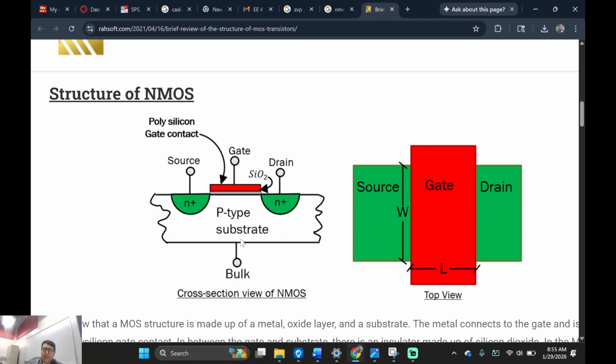So in industry, you have 2 types of substrates. You have the P-type substrate and there's an N-type substrate. But generally I've never seen an N-type substrate in my 5 or 6 years of working with IC design. Typically, it's always a P sub, okay? You're going to just be given some big fat piece of silicon doped with P-type material, okay? And P-type material has an extra hole.